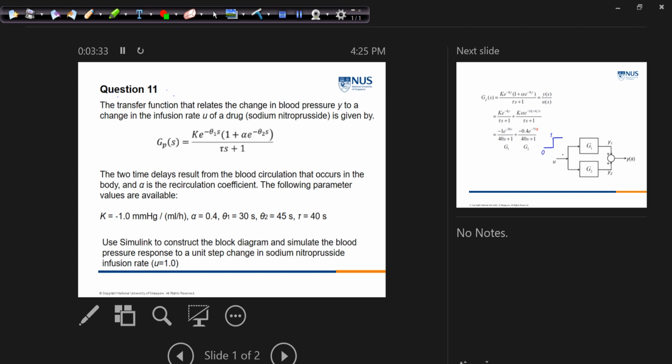This is a typical way to describe a realistic process using a model. When you think there's a time delay, you add a time delay term theta. When you think there is another coefficient to penalize, instead of just 1, you can consider it to be 80%, 50%. Then this alpha here is playing this role. Alpha at 0.4, as an example.